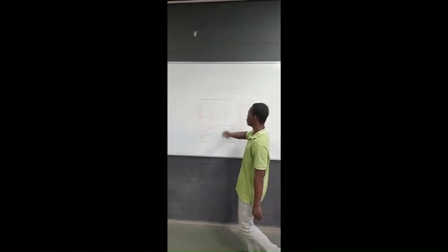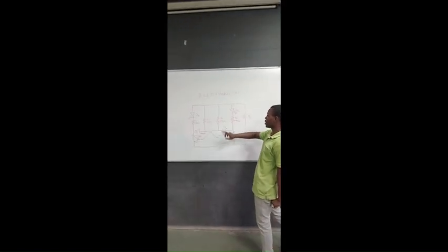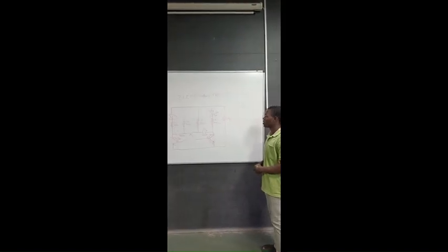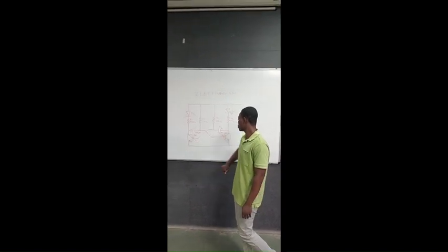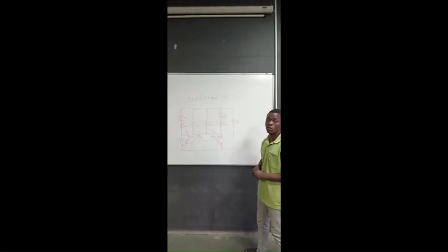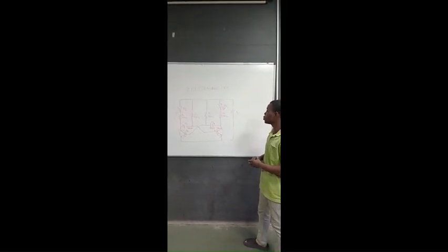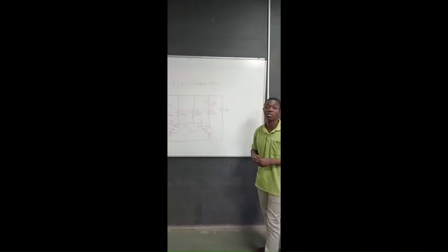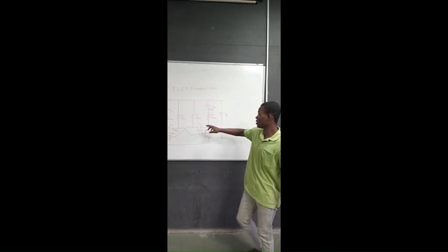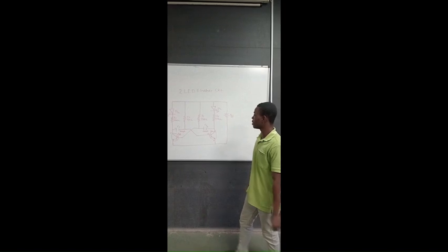Then we come to our resistors R2 and R3. Both of them, as you see, are 22 kilo ohm resistors. These resistors are connected to Q1 and Q2. Their operation is to control the switching behavior of the BJTs by controlling their base currents. That is the role of resistors R2 and R3.